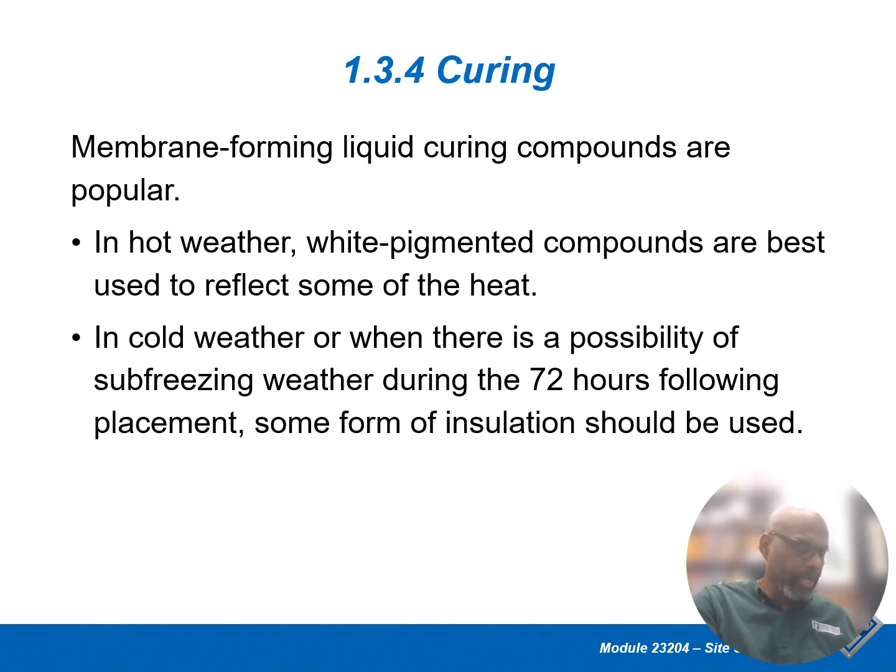They're using that white powder that they spray on, or sometimes it might be a liquid, a water, and they would spray it on when it's hot. Basically it gives a lighter color, not to color it, but just to reflect the sun away so it doesn't overheat the concrete. The darker the concrete, the more heat it can absorb. The more heat it absorbs, the faster it would evaporate. So again, this is to allow it to cure.